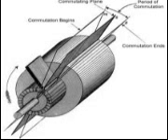Commutators. Figure 9-14 shows a cross-sectional view of a typical commutator. The commutator is located at the end of an armature and consists of wedge-shaped segments of hard-drawn copper, insulated from each other by thin sheets of mica. The segments are held in place by steel V-rings or clamps. Figure 9-12. An 8-section, ring-type armature. Commutator, slots, coils. Figure 9-13.